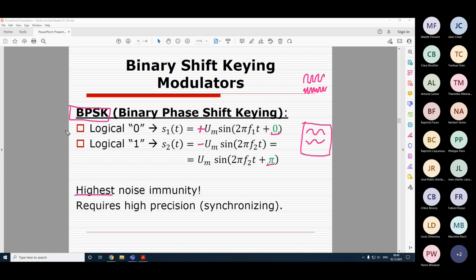The distance is so great that we have to use the strongest possible, most noise immune signal, use a very slow data transmission rate, use a lot of error correction coding and so forth, just to get that picture, to see what that planet looks like. So for that reason we often use binary phase shift keying there as the most noise immune. It is one of the slowest modulation types, but it is reliable, and reliability for that purpose is more important than speed.